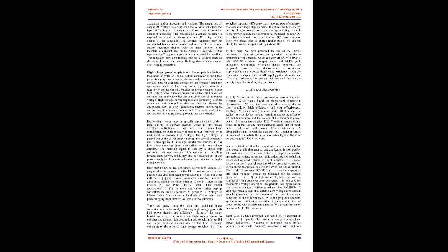The output voltage from a rectifier circuit has a pulsating character, i.e., it contains unwanted AC components, components of supply frequency f and its harmonics, along with the DC component. Most electronic devices work with a pure constant DC voltage rather than that furnished by a rectifier. Therefore, to eliminate the AC components from the rectifier, a filter circuit is required. Filter is a device which passes DC component to the load and blocks the AC components of the rectifier output.